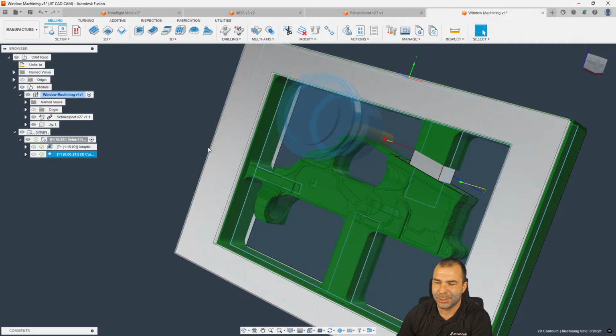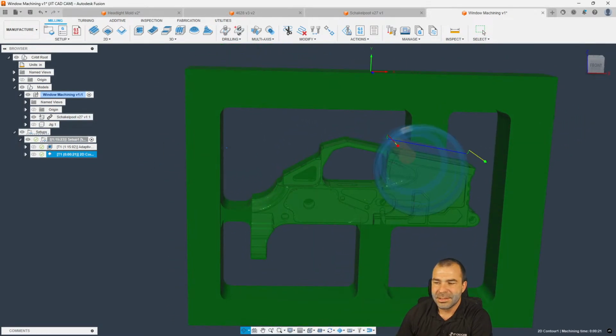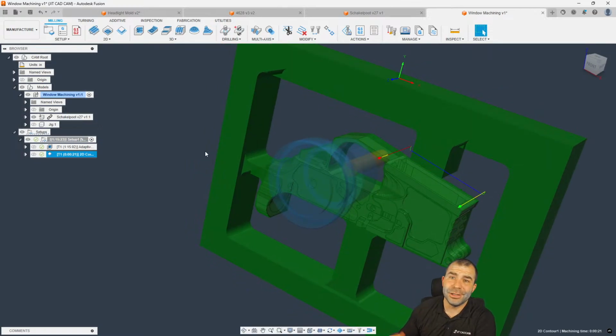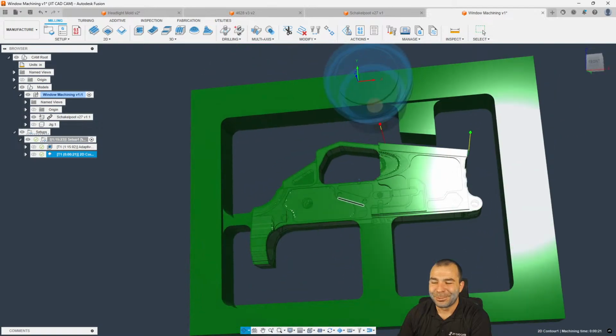Now you can see that goes all the way through that green stock, right? So that's how I would machine apart this side, that side, and then break it out, and away we would go. For anybody that's just joined, guys, yes, I know you would not do this part this way. I completely agree, right? You would probably do 1 or 2 tabs down here on the bottom, like when I show it in the video walking people through this.